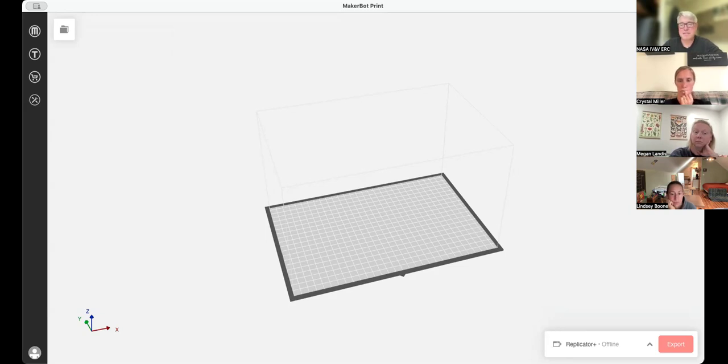So I ran out of plastic last night. I hit print and left work, and I was making one of these ramps, and when it ran out of plastic, it just stopped. So if you look here, inside the middle of my object is this grid pattern. That's because it's not a solid plastic piece. It would be very slow and very expensive to print a solid plastic piece. You can say, no, no, no, this has got to be really strong, I want solid, but generally you're going to choose what's called an infill. And the higher the value, from very little infill to a completely solid object, would change the honeycomb pattern that's inside of your object.